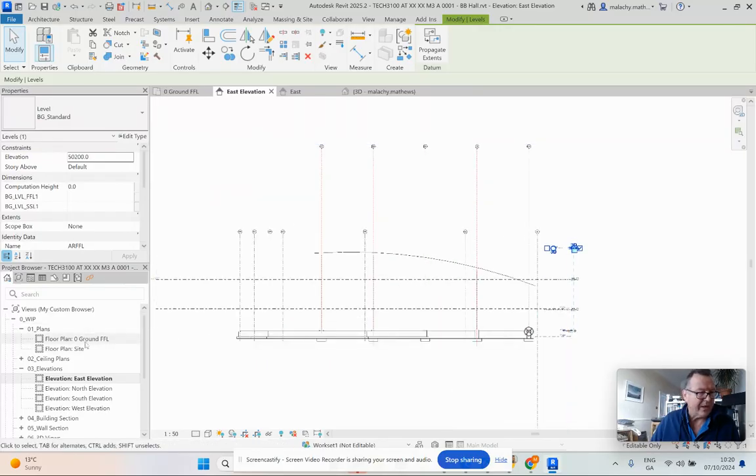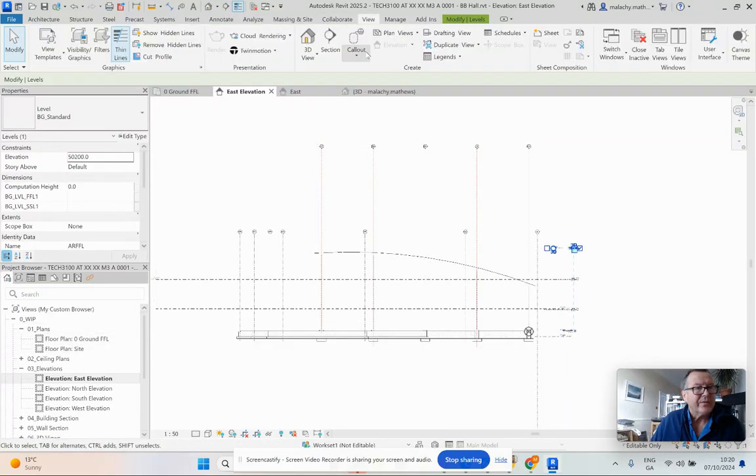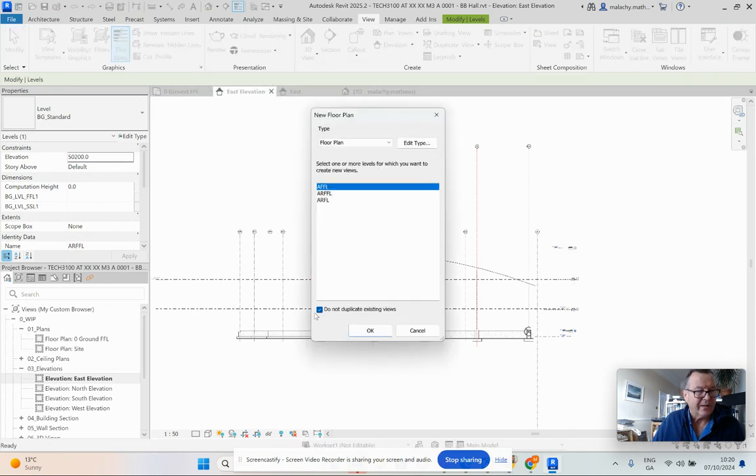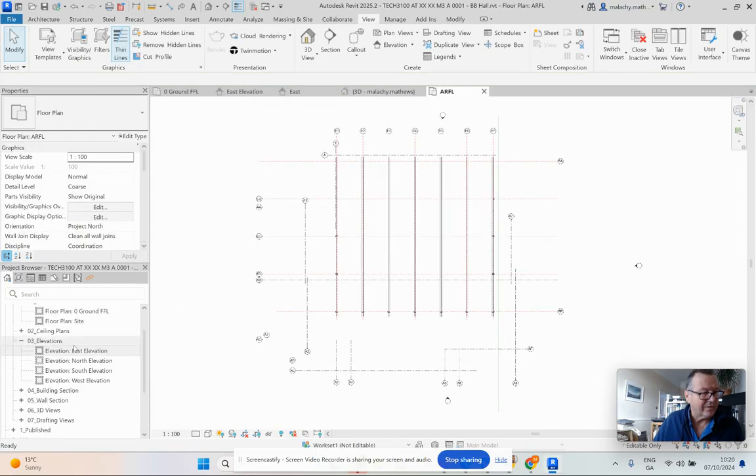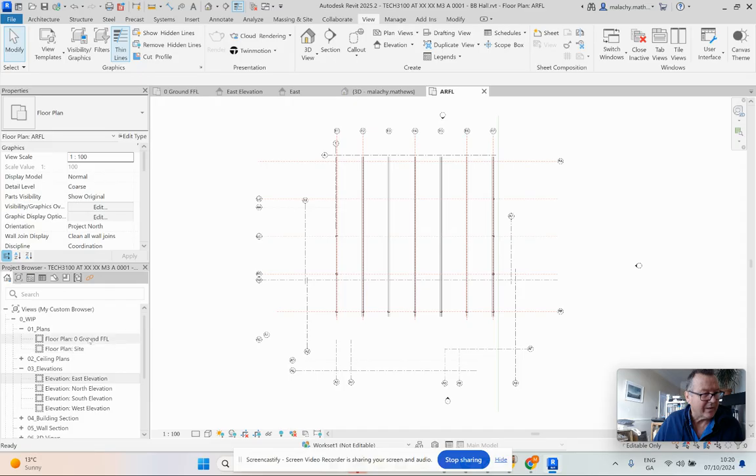All right. Now, how do I get these across and into here? We will go into our views and into our plan views, floor plans, and we will select each of those and go Update, right? And there should have come down. They'll be in the question marks here.